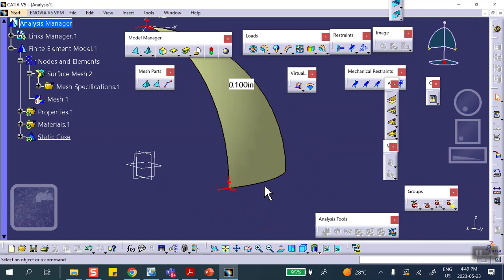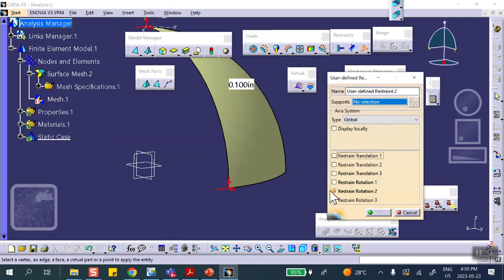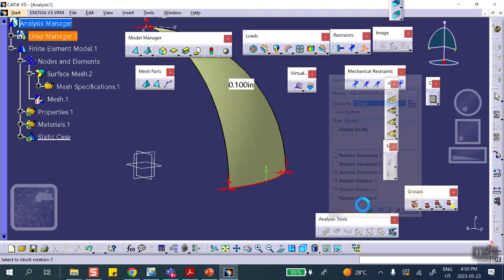This bottom edge is in the XY plane. Global. Again, user defined. However, it really doesn't matter. It's in the XY plane, that's fine. So let's do this. It does not move in the direction Z, and rotations are opposite that edge. Don't forget to do the global here.